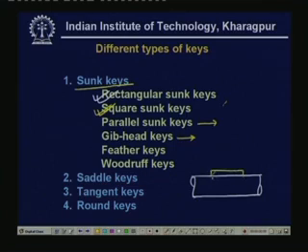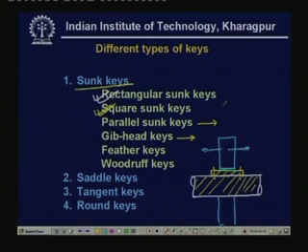It may be machined this way, or it may be set by a set screw. It may be screwed here, and we put another disc with a key slot cut into it and then insert. So if you move it this way or that way, the key provides enough flexibility in moving in axial directions. So this is the feather key.